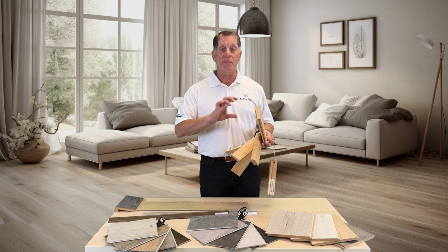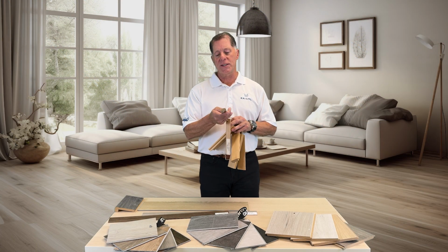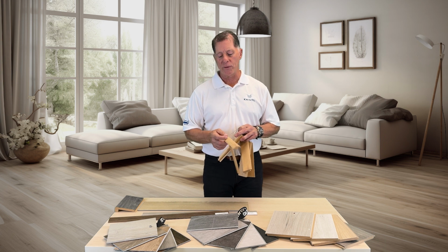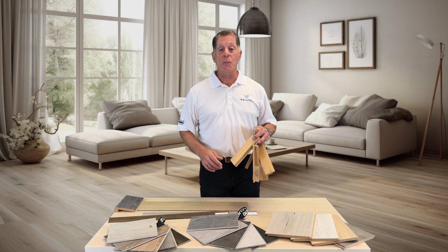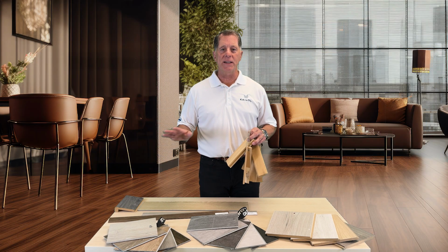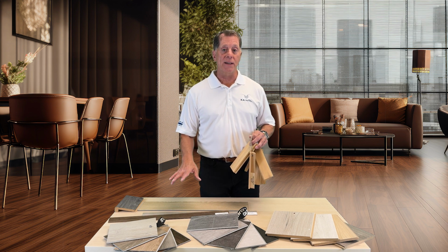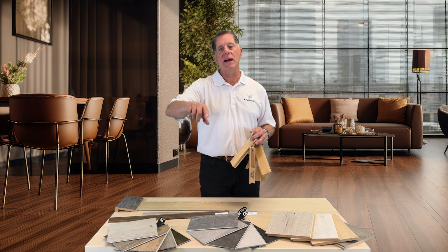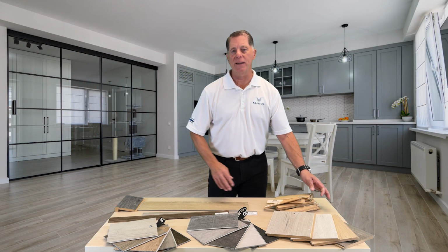Typically, you will also have baseboard molding around the perimeter of the room and potentially shoe molding, similar to this piece right here, this very small shoe molding piece. Or you will have quarter round, and that quarter round will also go around the perimeter of the baseboard, and that gives a very, very nice, clean, finished look. And in the case of laminate flooring, as well as SPC, it will also cover the expansion space that needs to be left around the perimeter of the room so that the floor can naturally expand and contract.